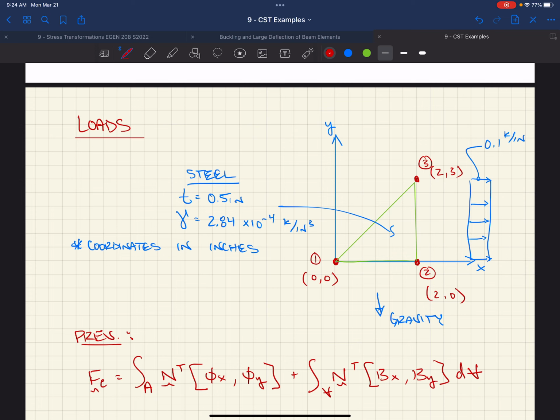We could also have, in this case, this is called a traction. We also could have, as we talked about in class, a line load. That line load might be coming from a shear wall that's landing on the floor that we're standing on, right? So maybe this wall here is a shear wall. It's getting load from the diaphragm up above or the roof up above that. It's coming down, and maybe this wall is discontinuous. Maybe this wall doesn't extend into the basement, where there's a basement below us.